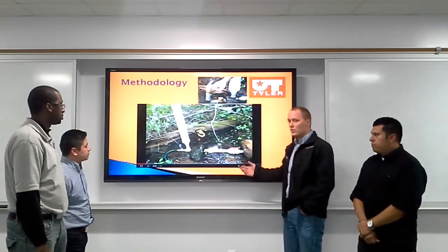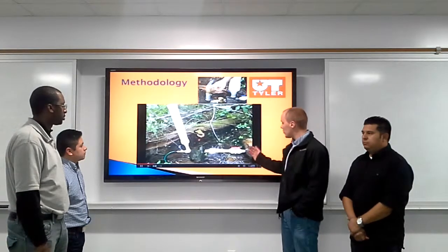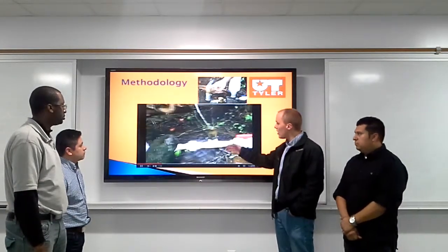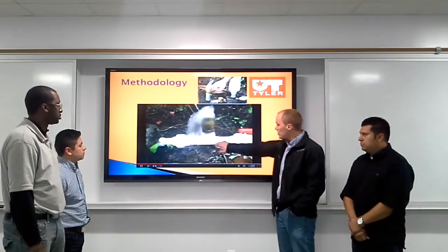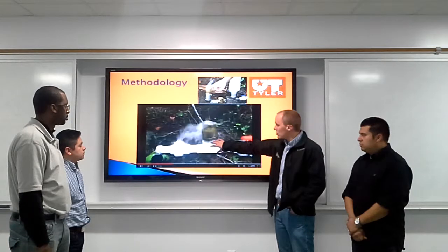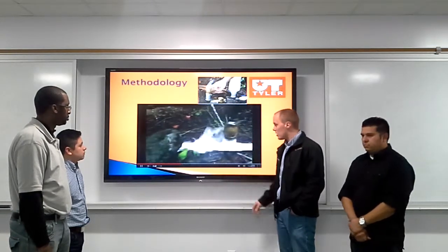Here's a video of a ram cycle currently in progress. Water flows through the inlet and out through the now primed system out of the waste valve. Pressure is constantly building up right below the waste valve, and eventually the pressure overcomes the weight of the valve and slams the gate shut.